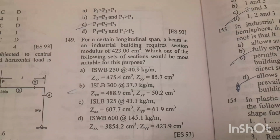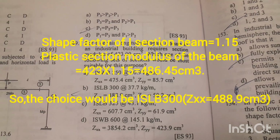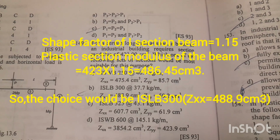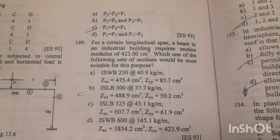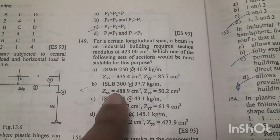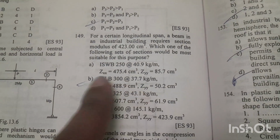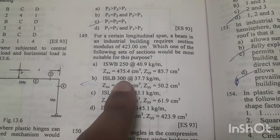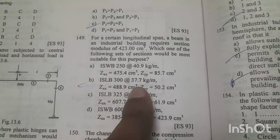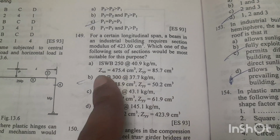Plastic section modulus will be equal to 423 into 1.15, which is nearly 487 cm3. So a Z axis of 488.9 cm3 will be suitable. We can use ISLB 300 at the rate of 37.7 kg per meter. Option B is the right answer.